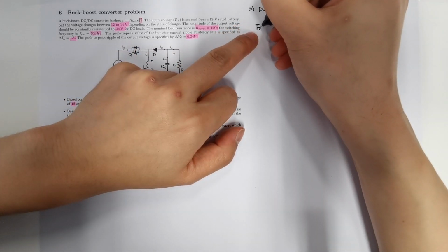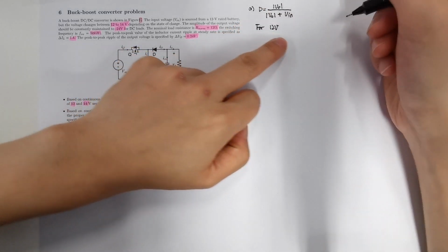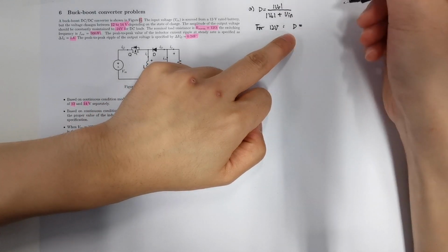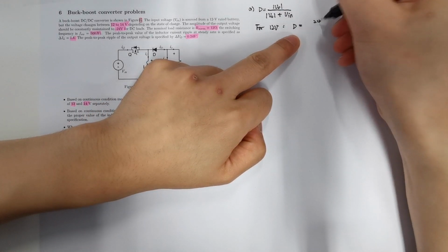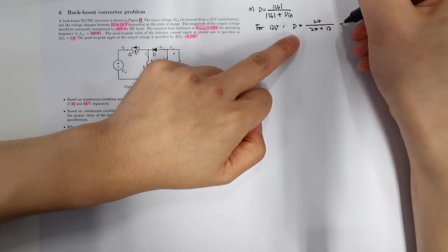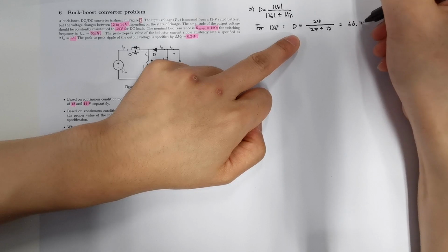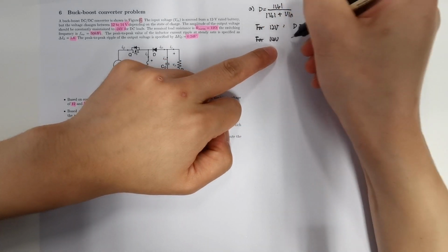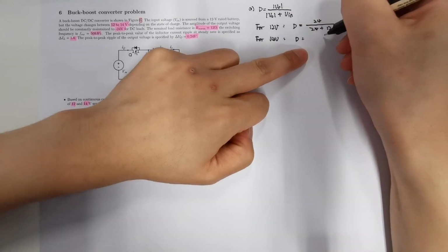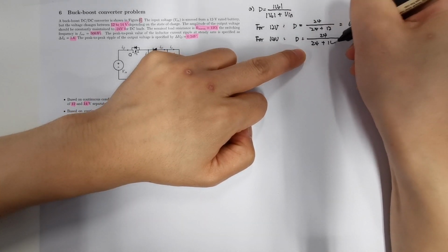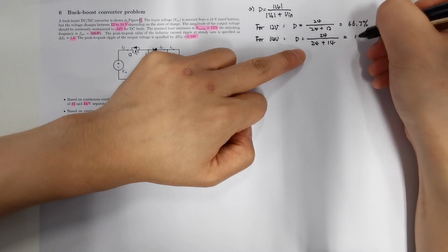For 12 volts, our duty equals 24 divided by 24 plus 12, which is 66.7%, and for 14 volts our duty is 24 divided by 24 plus 14, which is